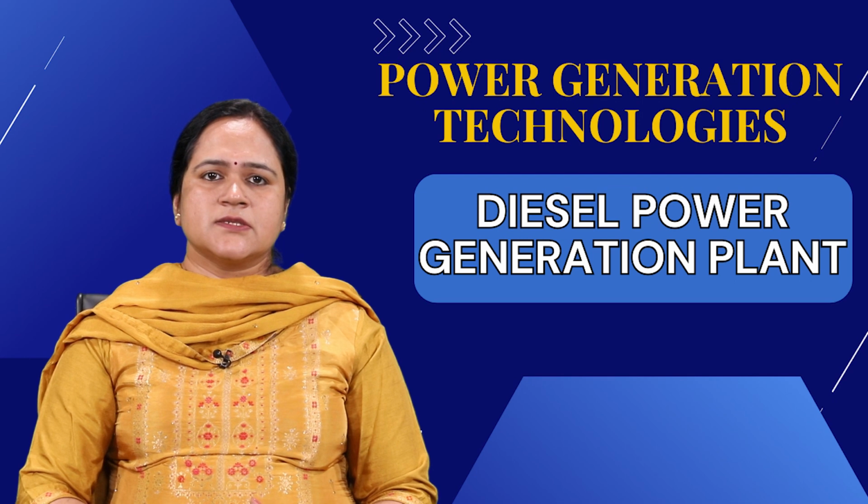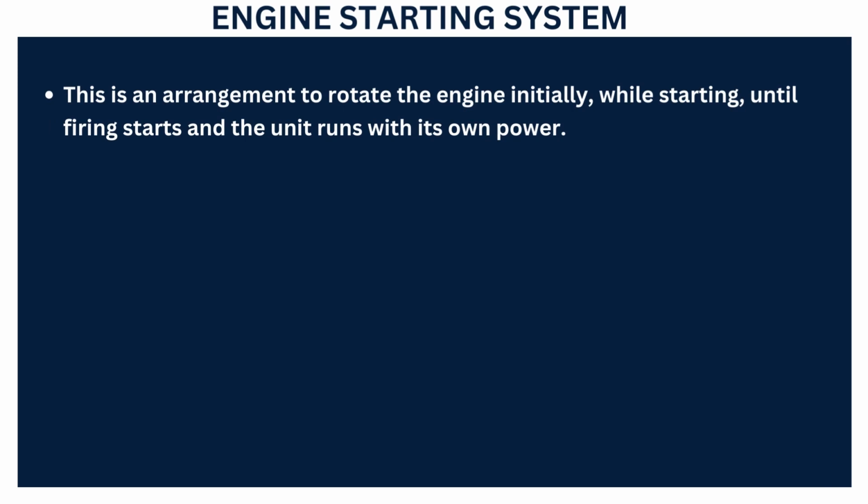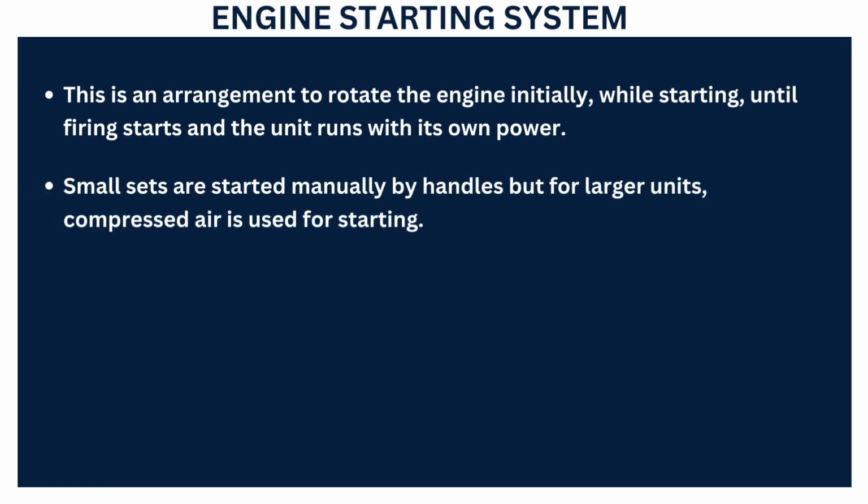Then the engine starting system: how we are going to start the engine. This is generally an arrangement to rotate the engine initially. We have to give the initial torque or momentum while starting, until firing starts and the unit runs with its own power. This is the arrangement for that particular time period. Small sets are started manually. You might have seen in diesel generators there is a handle and we have to rotate that handle. But for the larger units, we use compressed air for starting.